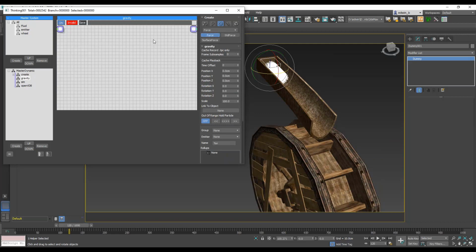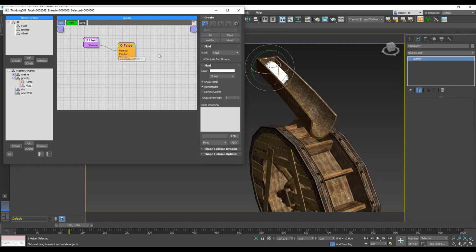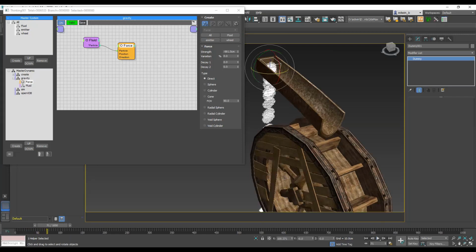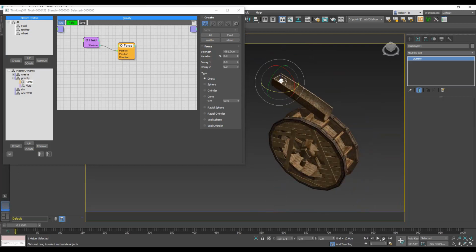So in the force section, we see our standard force. And here, again, the procedural approach is so easy and so effective. We just decide here our fluid particles should receive the force. And we are in centimeters, so we need to make sure that we're properly scaling our force to 9.8 meters per second. And that's actually it. Once more, we restart our simulation, play back our simulation, and here we go. Yay, we have our simulation here and particles falling down.